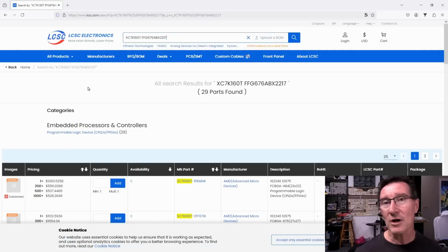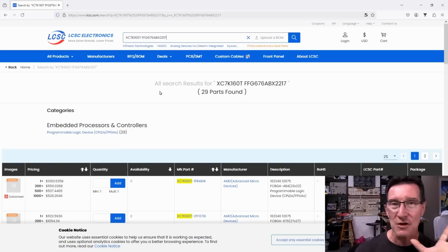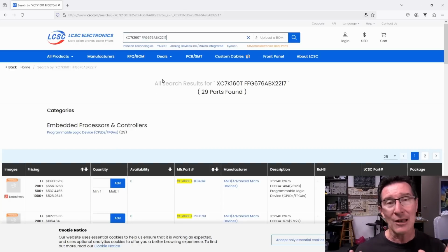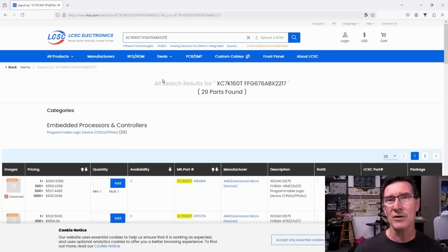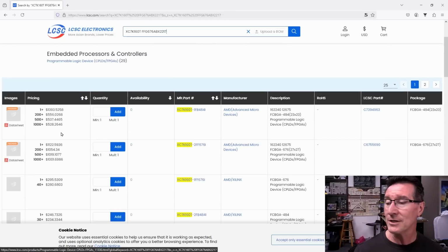And for most of these pricings, I'm going to use LCSC, which is basically China's equivalent to DigiKey, Mouser, Farnell, that kind of thing, Element 14. So it's their catalog distributor, but you can get a lot of Asian sourced components there. When you're doing BOM cost analysis like this, it's probably better to use this than DigiKey or Mouser, because you can often get cheaper Asian pricing.